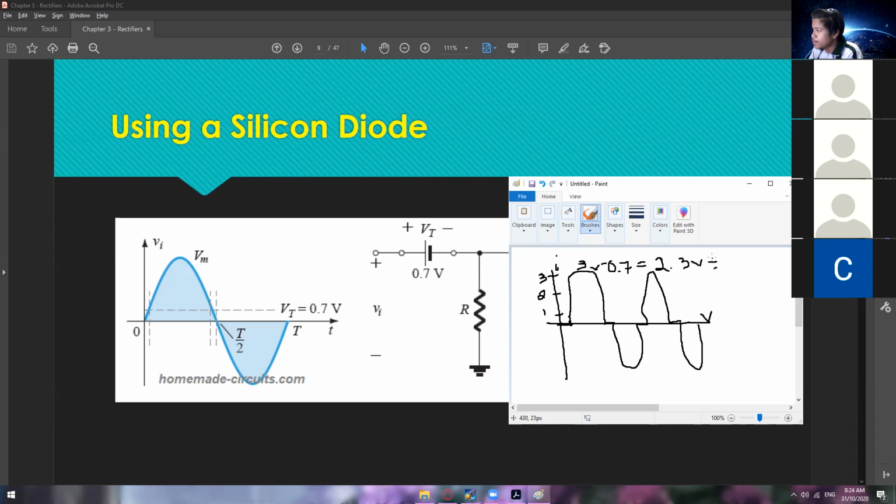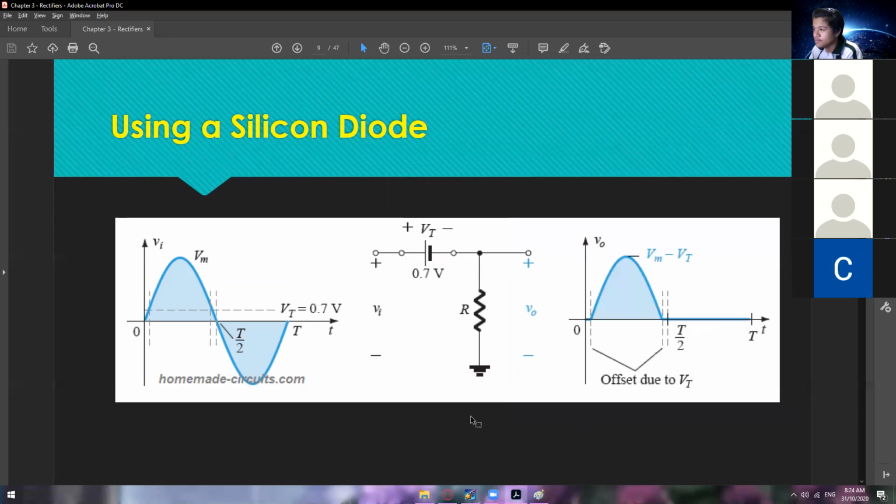So this is our VM. Same idea, of course, this will not conduct at the negative half cycle, since if this is negative and then this is positive, then this will make the diode reverse biased.